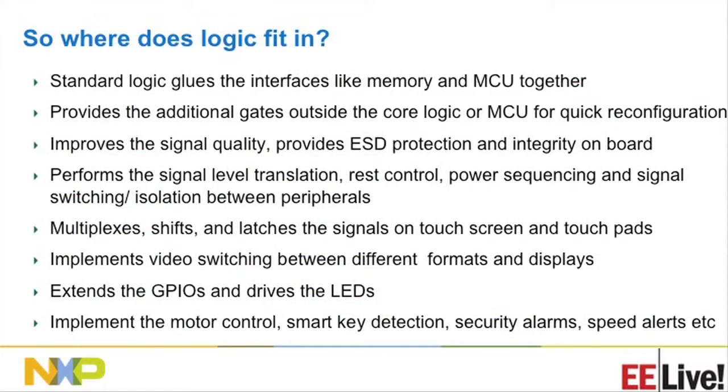So looking at the standard logic, today it's gluing the different interfaces like memories and MCUs together. There are some additional gates outside the microcontrollers for quick reconfiguration. It's still improving the signal integrity and signal quality. It also does some ESD protection. On the boards, it multiplexes, shifts, or latches the signals, and sometimes we do extend the GPIOs and drive the LEDs with them.